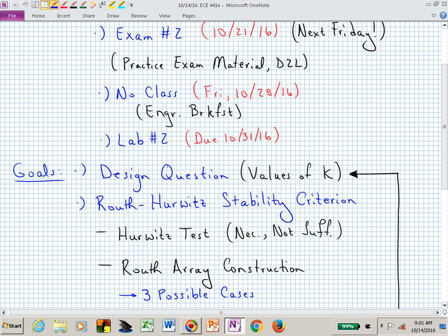The main problem that I was seeing with some of the labs was, one, you were getting the weight wrong. The weight or the mass is supposed to include the carriage. A lot of people didn't include the 0.5 kilogram contribution of the carriage, and they were also maybe getting the time to peak wrong. If they were getting a time to peak of 6.19, they were saying, oh, I have a time to peak of 6.19, but it's really relative to when you actually kicked the system, and you kicked it again at 6, and so your time to peak is 6.19 minus 6. Some people were getting a very, very tiny omega sub d because they were using that large 6.19 number for their time to peak. It's really that time difference between when it gets kicked and when you see the peak subsequent to that.